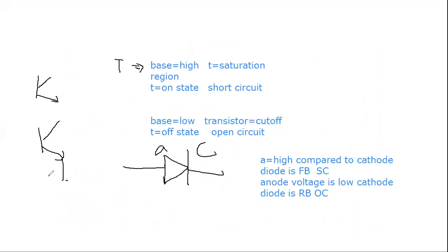So this emitter, we are going to connect it to the ground, and this is connected, shorted, and here through this resistor. Sorry. Here you just take the resistor, which is RC, and here you just take the V0 voltage, and here you just apply VCC.